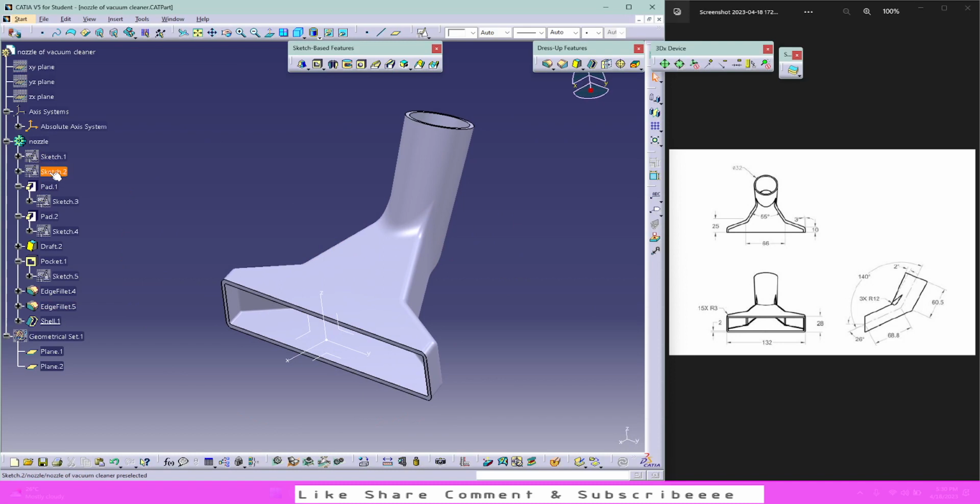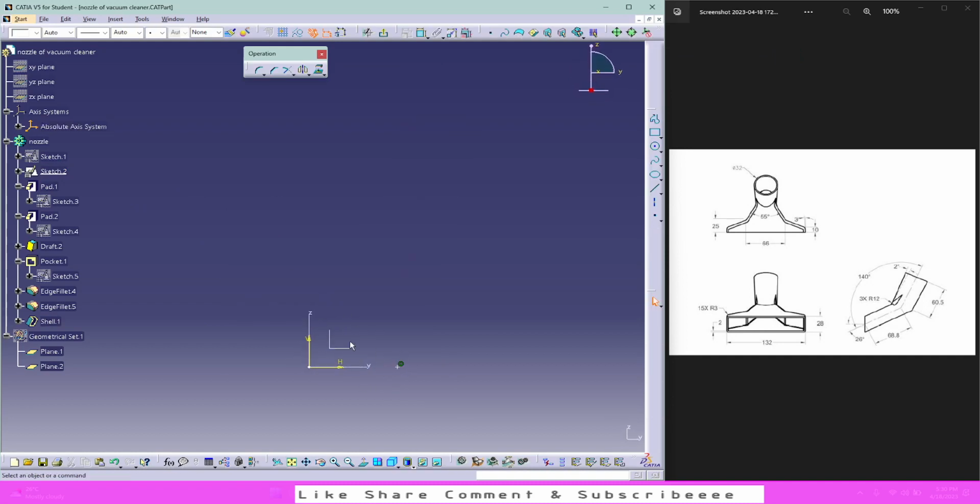After that, what I did is I just created a simple point. So right now I've hidden it. So basically what I did is I selected the YZ plane and created a random point on the horizontal axis, constrained to the horizontal axis. As you can see, this is the constraint symbol. So after that I will exit again.